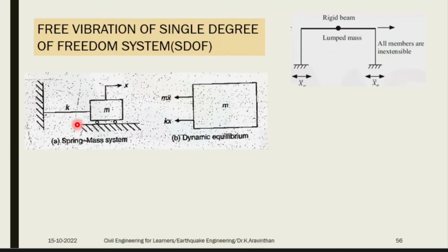This is called modeling. This end is fixed, hence you are applying fixity here. How many columns are here? You have 2 columns. The column has to be taken and assumed only as a stiffener. The column is not carrying any vertical load. Now you have to imagine differently.